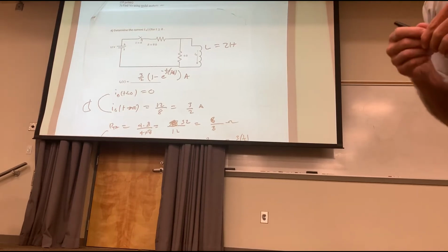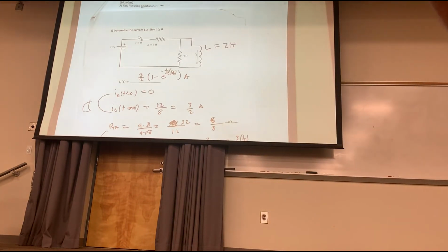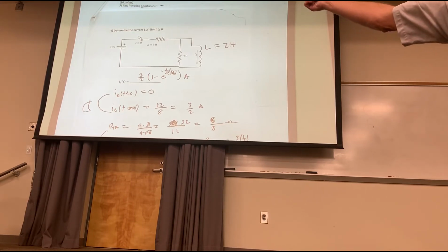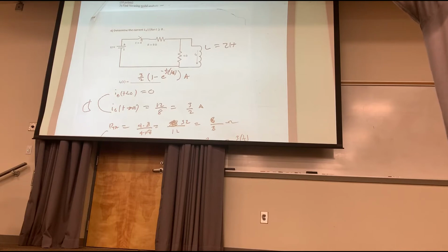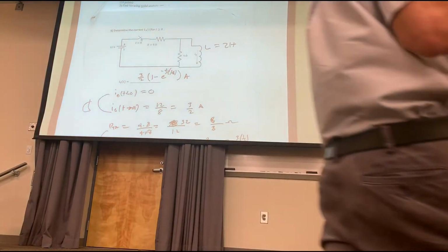That flows. The next thing you need to do is find the Thevenin equivalent resistance after the switch closes. After it closes, you have 4 in parallel with 8, because the source voltage looks like a short, doesn't it? 4 in parallel with 8, not in series, in parallel. That means tau is equal to R Thevenin times C, correct? And then you can assemble your solution.